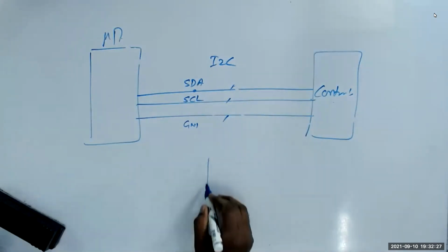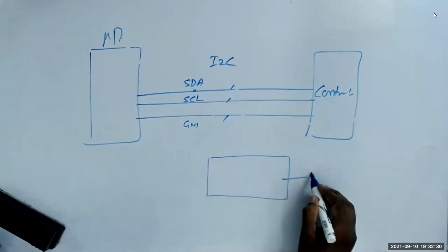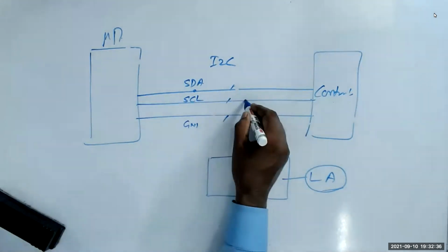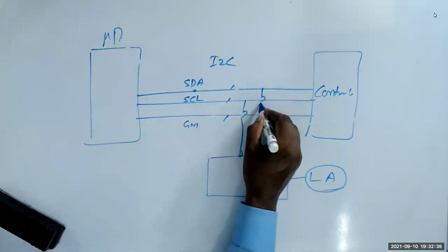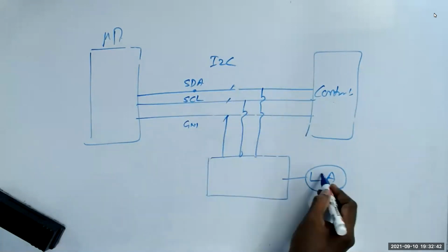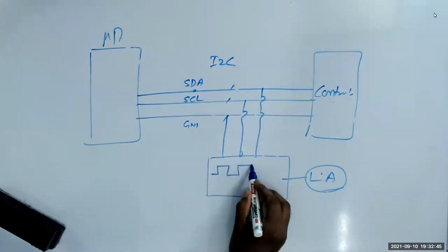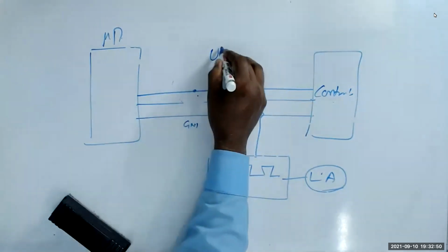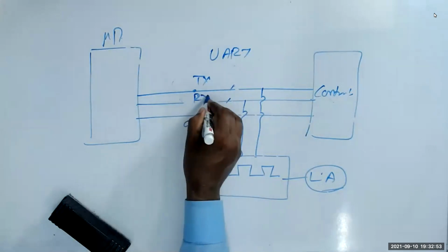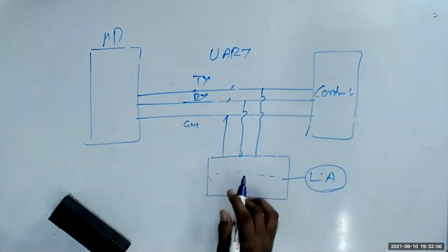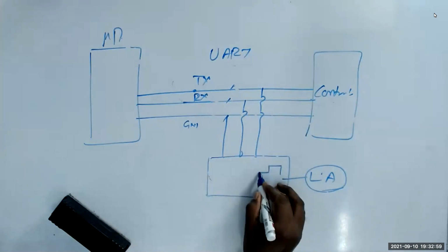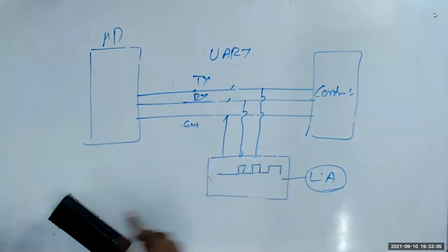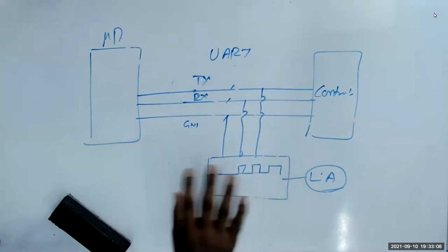That's what I told you, learn to debug from the beginning itself, using a logic analyzer. If you like to understand these things, the easiest way is a logic analyzer. There you will see the actual signals. Let's say UART, TX, RX. You will understand exactly what is happening. Oh, start bit, 10 bits, stop bit. You will see the 8 bits here. What is the waveform? How much time you are sending? All the things can be seen on this.